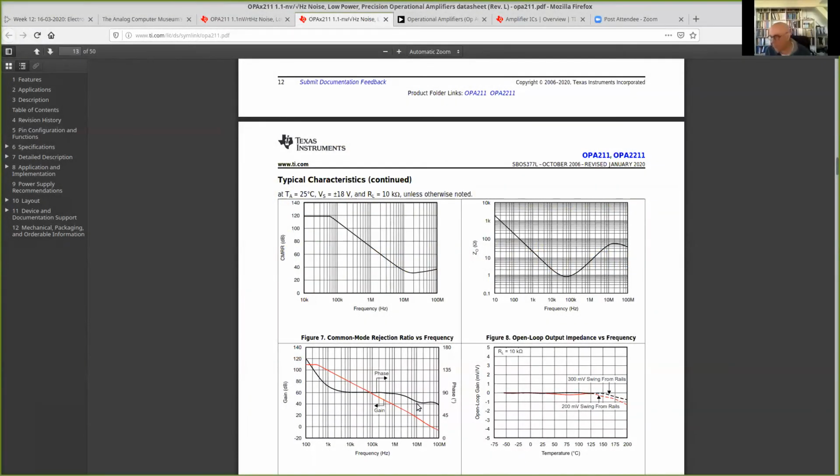If you want to make an application of this operational amplifier, and the bandwidth of the amplifier that you are making should be in the order of 10 megahertz, then of course your model should at least be good up to 10 megahertz. But we will find out in the next lecture that non-dominant poles can have a significant influence on stability.